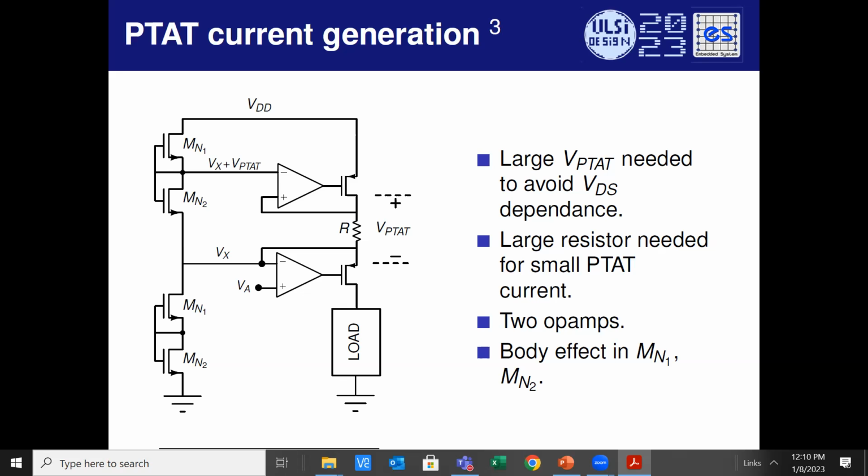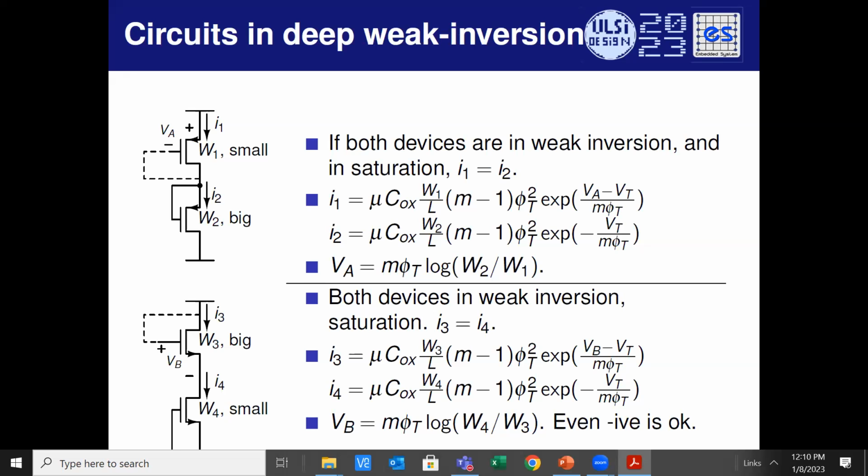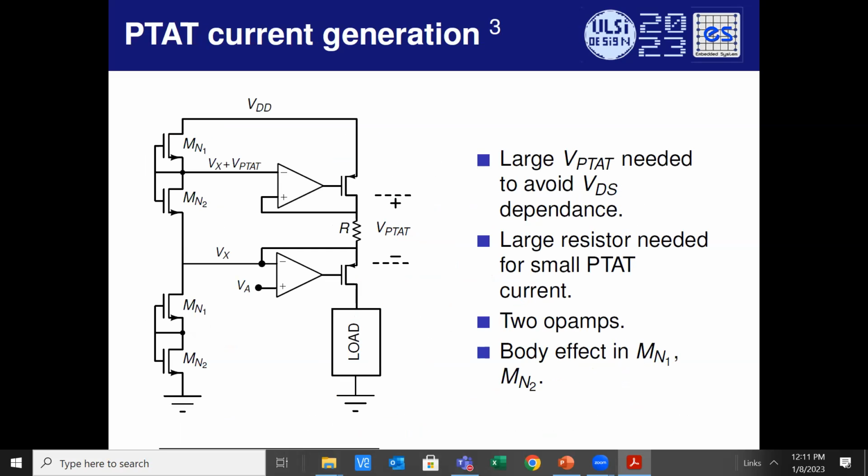All right. So based on what you have seen over here, if I have PMOS, then the gate to source voltage of the upper PMOS is a PTAT. If I have NMOS, gate to source voltage of the upper NMOS is a PTAT. So this particular concept was used in this work. This is also coming out of the Michigan people, Dennis Sylvester and Blaauw. The reference is hidden.